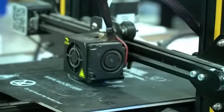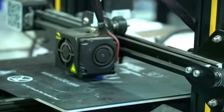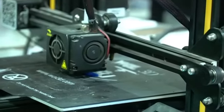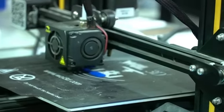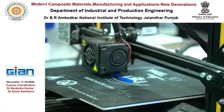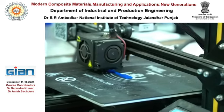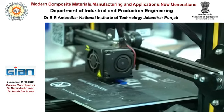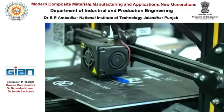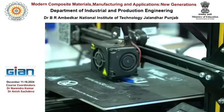Suppose I decrease the infill density. Currently, what have you used, 100% infill density? Because we have selected 100% infill density, since we want to test the specimen. We have modeled the tensile specimen, and that specimen will be used to test the strength of the material. That's why we have given 100% infill density. But if you want to reduce the density, just reduce the density and show the consequences. If you reduce the density, what will happen?